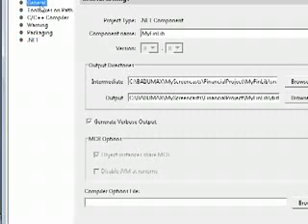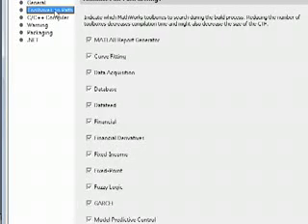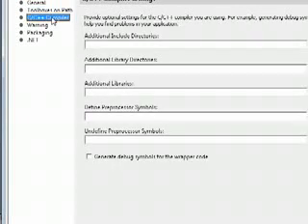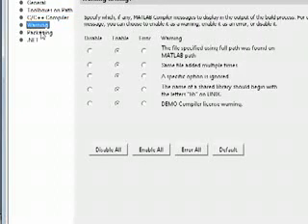And there are a number of other options you can specify. The component name, you can specify a different component name, and generate verbose output, toolboxes path, C++ compiler, additional include directories, etc. Warnings, packaging. In packaging you can see include MATLAB component runtime. If you are using these assemblies on a different machine where MATLAB is not installed, you require certain runtime libraries to run your algorithms.